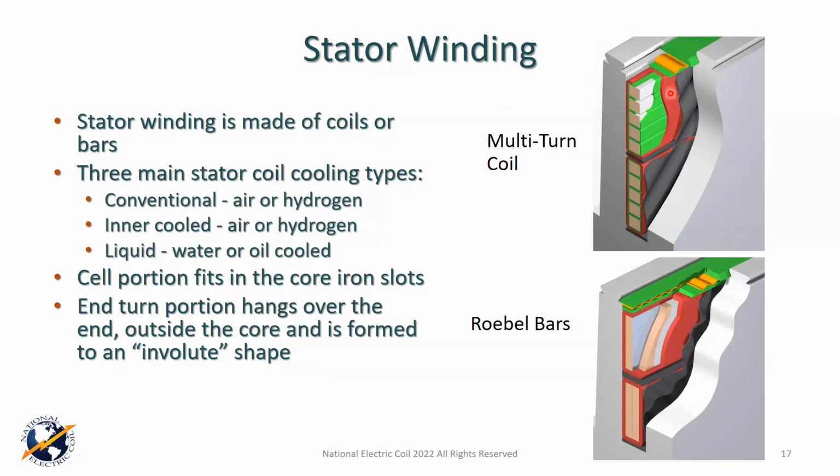I think one of them is still 62 and a half. It used to be 60 volts per mil, but that's been increased. But you should look at what you think is right for you. Talk to the coil manufacturer and the company doing the rewind about what's good for them. You might want to mention the turn insulation as well, but these are good things to have in your spec and be considering long before you do your rewind.